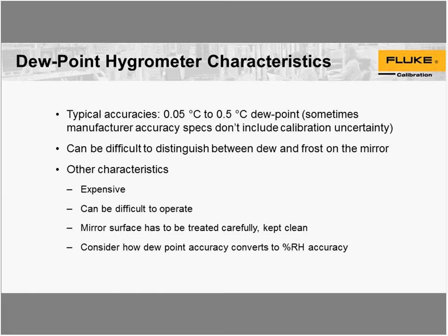As a matter of fact, I've seen with our own chilled mirrors that even at dew frost point, again, it's hard to know where you're at when you're down in this region, but when you're below zero, as low as -18, I've sometimes seen dew on the mirror, and sometimes it has frost on the mirror at -18.